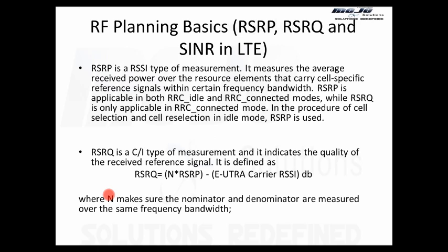You should understand what RSSI itself is. Well, you are standing in the middle, and you have a lot of base stations transmitting around you. You can receive the signal from all the base stations. The combined signal strength on that frequency from all the base stations is RSSI. Simple. Is there any question about RSSI right now? Or is it clear? Okay, sounds good. I'll move on.